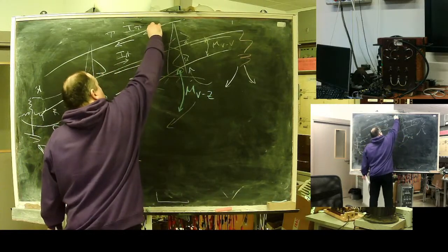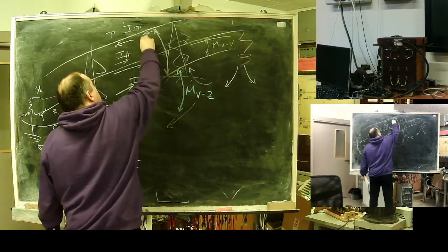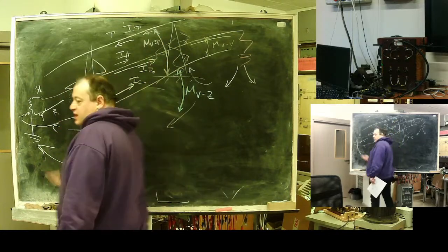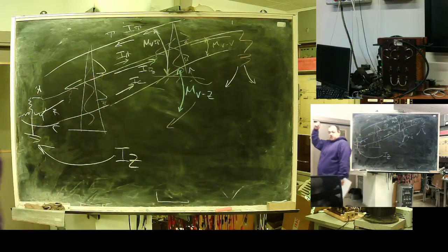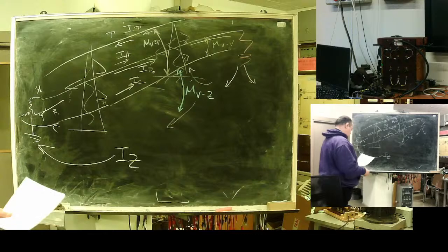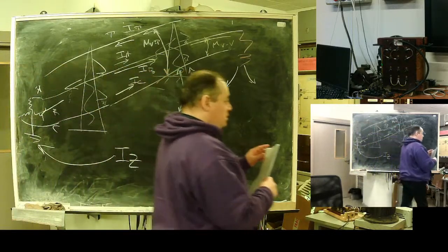You also need to tackle coupling between wire and lightning protection. A whole set of mutual inductances. You need to account for all of this to get real electrical values for your model.